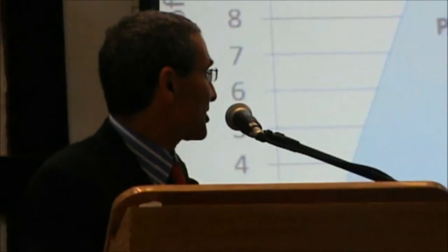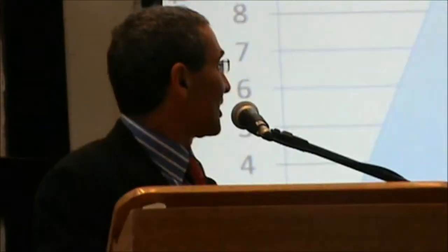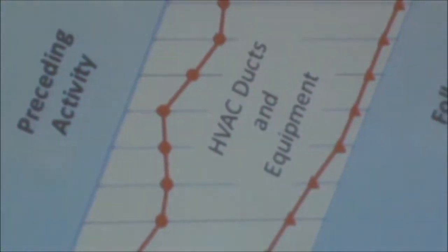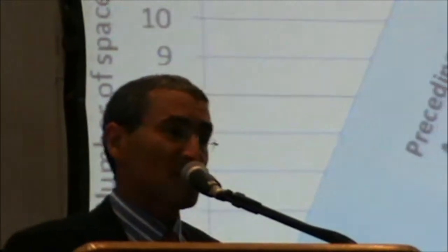And if I show you the red curve, then you can do this. So now you see that this has moved forward 7 weeks. And if you think that there are not one contractor, but 15, 20, and they're doing 30 to 40 activities on each department or each space, then this accumulates very fast. And so you get much shorter durations with less labor. And these are exactly the kind of experiments we can do with discrete event simulation.